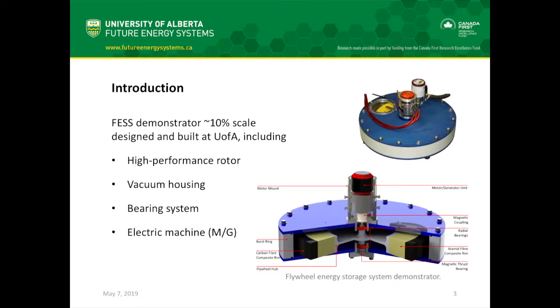Initially, as flywheel energy storage technology was evolving, the rotors were made of steel. But the disadvantage of steel is that the RPM was much lower, in the range of 10,000s. Rotational energy is directly proportional to the moment of inertia and angular velocity. With the development of technology, the rotors are now made of composite materials, and they can be made of different rims of composite materials according to the application.